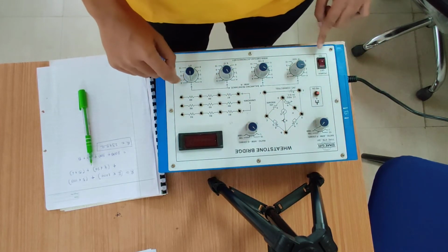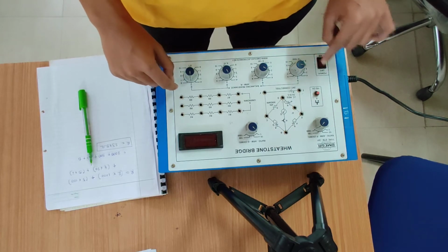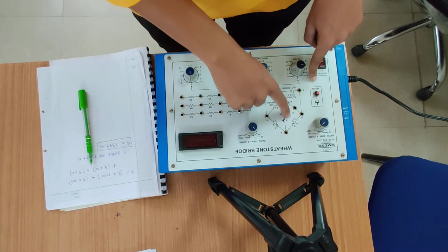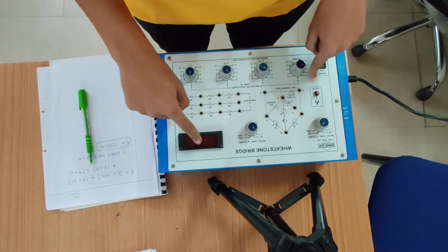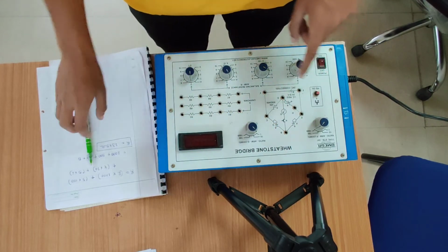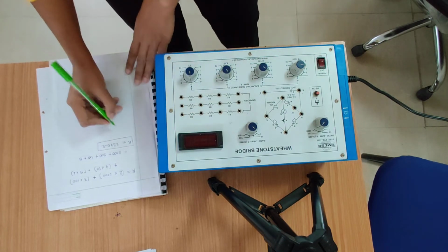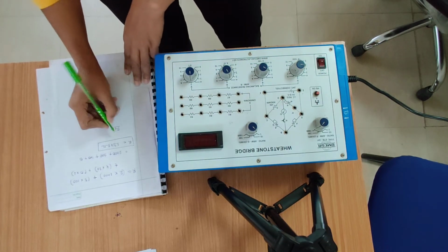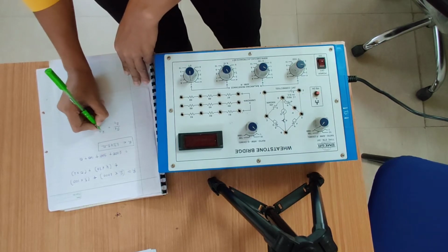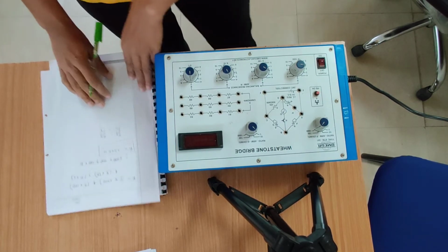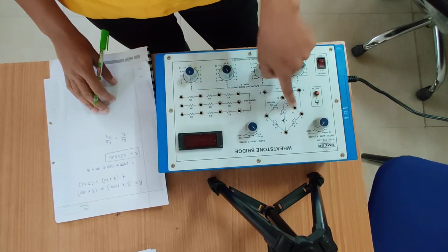That's why. So this is the power switch. This is the push button switch, which will connect the galvanometer to these 2 points, so that we can find the value of the galvanometer. Okay. As a Wheatstone bridge, we know at balance condition the equation is R1 divided by R2 equals R3 divided by R4. This is R1, R2, R3, R4.